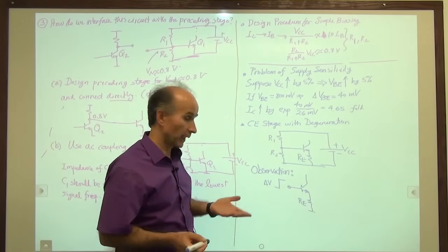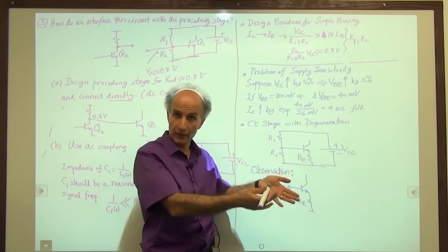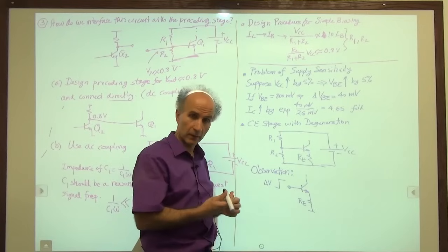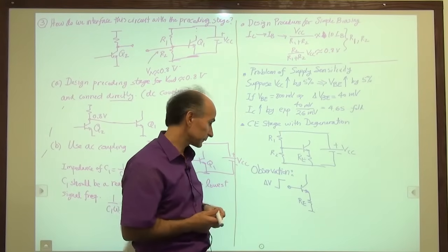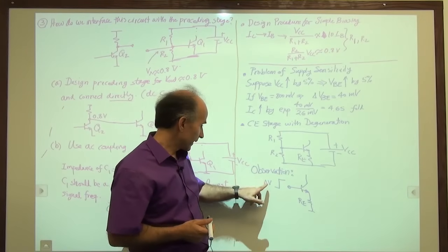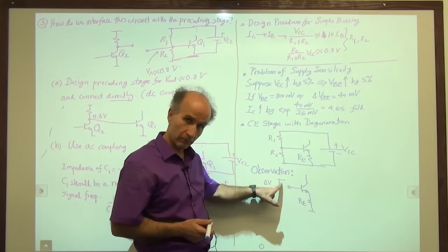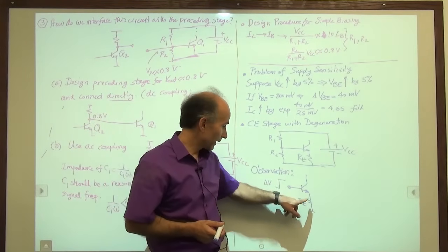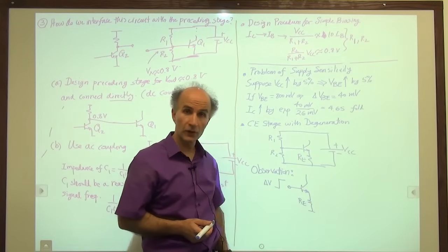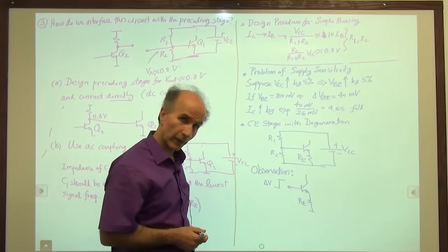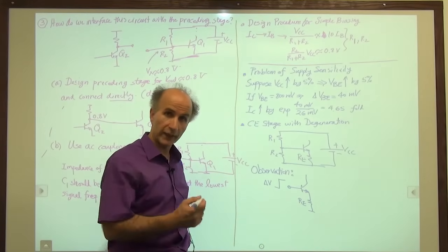Well, we can pick one of them and proceed and see if the result agrees with our assumptions. If not, then that assumption is incorrect. All right, so let's say delta V raises the base voltage like so, and let's assume that the emitter voltage doesn't change at all. Okay, so would that work?